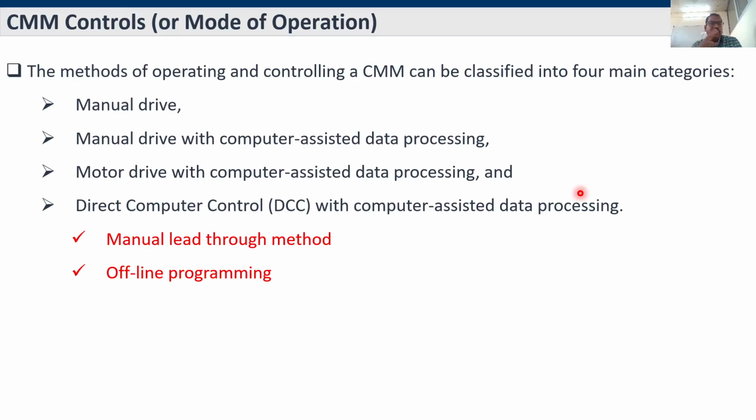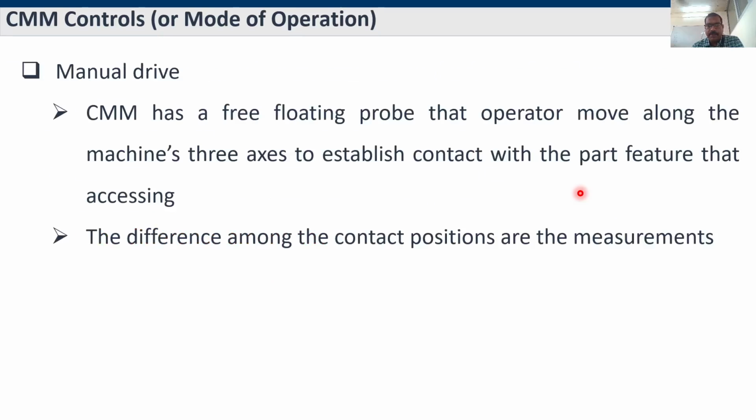Otherwise, with the 3D model inside your database, you can write a program through something like Robot Studio software. In a CMM also, you will have inbuilt software according to the company which provides the CMM. In that, you can write some offline programming. Then you can run it. Then automatically your probes or table will move according to the inputs.